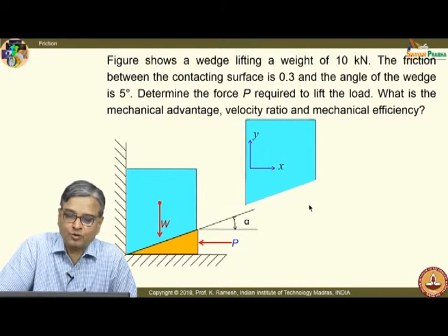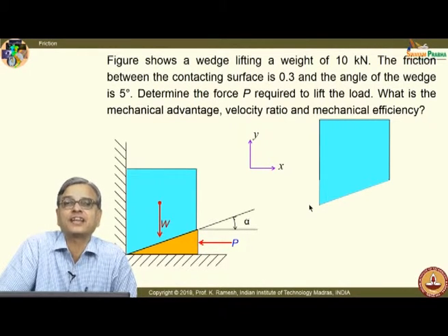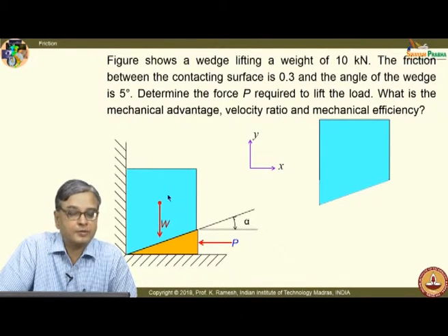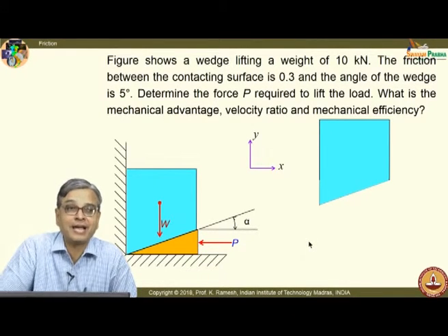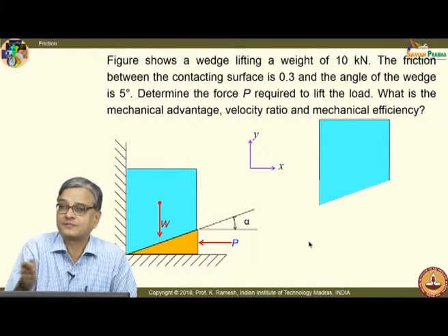And you will have to draw the free body, and in all problems dealing with friction, you have to indicate the frictional direction correctly. Here I am driving the wedge into the block W. So, what way should I indicate the frictional force? Because I am driving the wedge into it. Okay, you are deliberately applying a force in a particular direction. You have to recognize that.